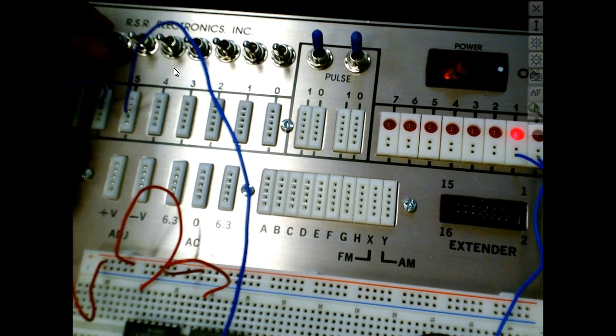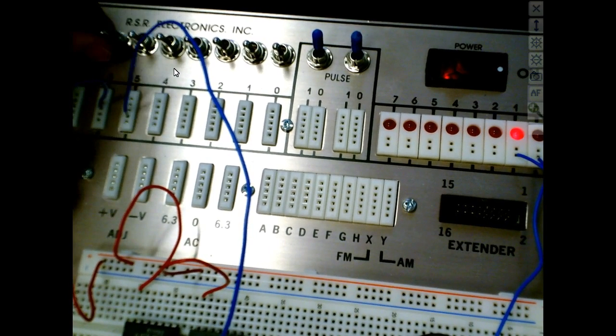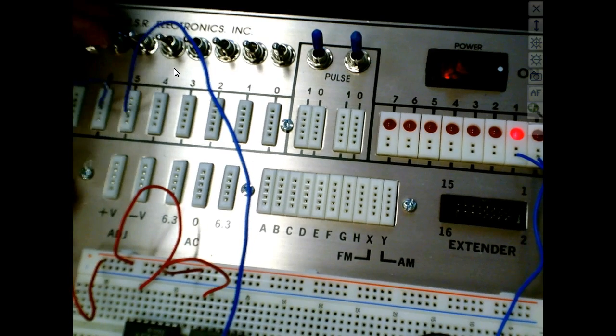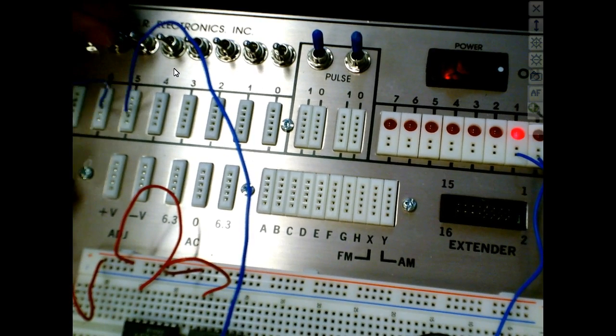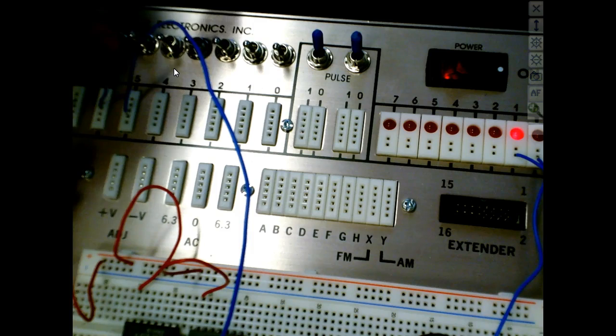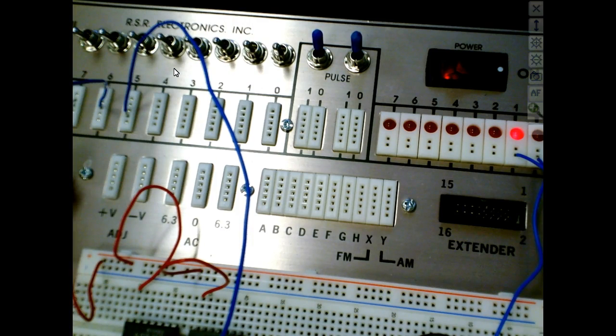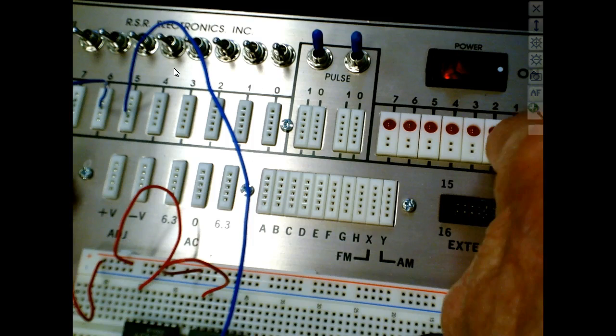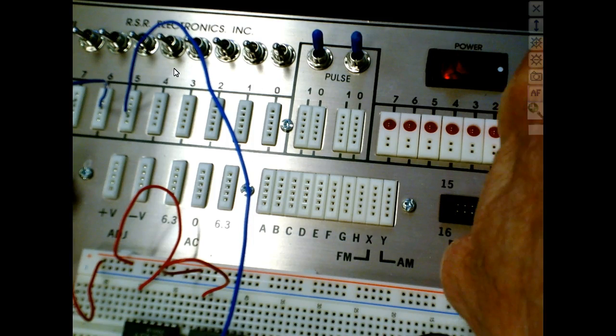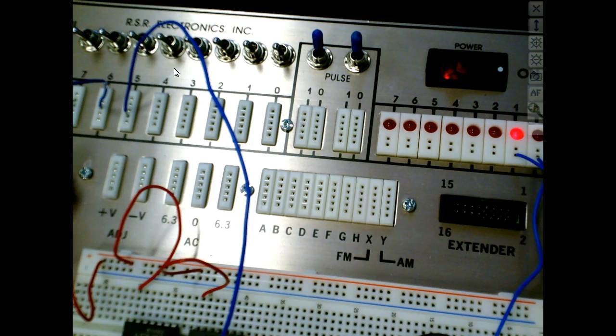They don't mean anything. Why don't they mean anything? Because it's disabled. Okay, you see that? Yes or no? Okay, I'm going to bring the reset. What's next? It says I need to bring the reset 1. By the way, let's do the Q and the not Q each time, right? So this is the Q. This is the not Q. The 1 is the Q, just like a while ago, and 0 is the not Q.